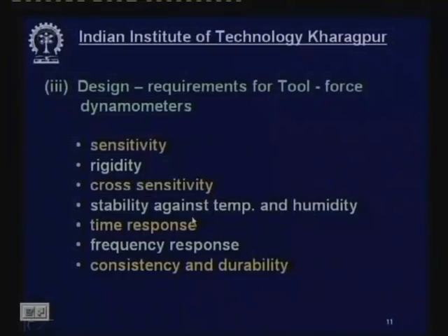Time response. The response should be very quick. The cause is the force, and the effect is the deflection, the strain, stress and so on, and the voltage. This should be simultaneous, almost simultaneous. If there is a lot of gap between the cause and the effect, there is a chance of error in the measurement. So the time response should be very quick.